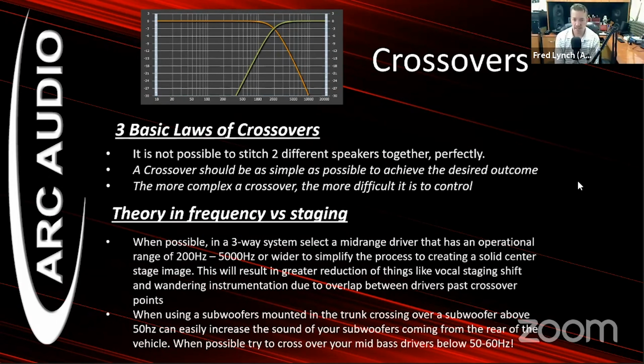When possible, in a three-way system, select a mid-range driver that has an operational range of at least 200 hertz to 5,000 hertz. The reason being is 200 hertz to 5K in a three-way system in the front of the vehicle holds a lot of the key staging frequencies in a system. And the more speakers you have playing through that range, the harder it is going to be to get your staging where you want it to be. For those of you that are new to this, staging is where the sound sounds like it's coming from in the vehicle. Instead of sounding like it's coming from the doors, it would sound like it's coming from up top on the dash with maybe a tweeter or a mid and tweeter in a three-way.